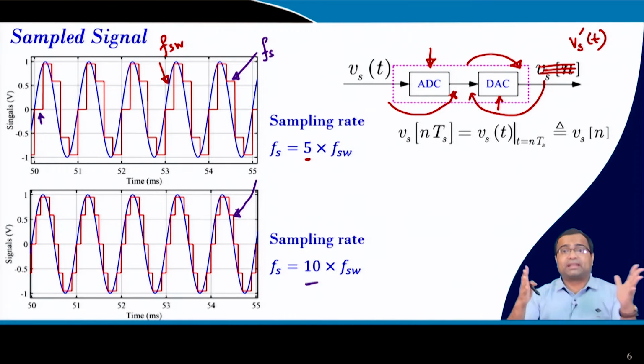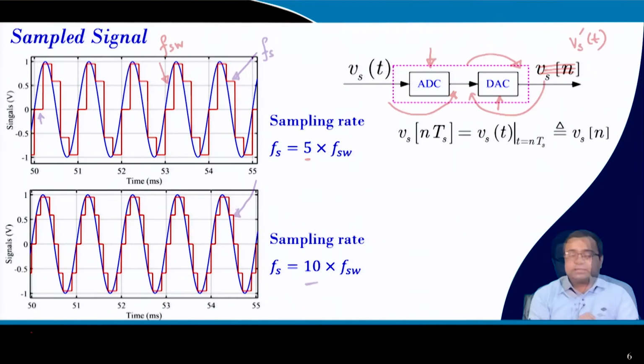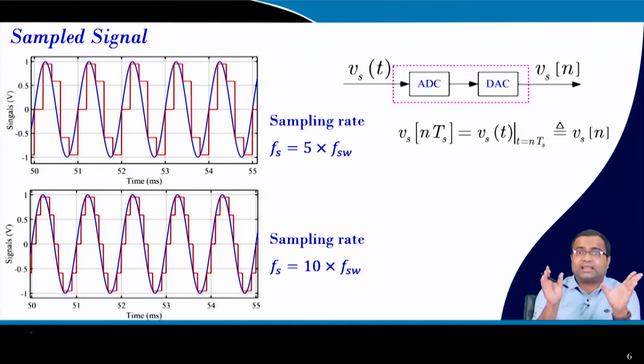It is simply impractical, because we are going to apply such sampling in our switching converter, in which the switching converter itself is running at a high switching frequency. So, we have little flexibility to increase the sampling rate; we cannot impractically increase it. Even if you want to sense a periodic signal, even if we take negligible variation in the time period, it can so happen that the sensor can have some uncertainty. The distortion in the sensor can also add up to this kind of variation.